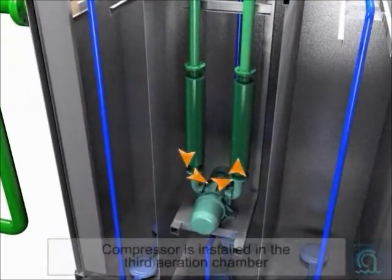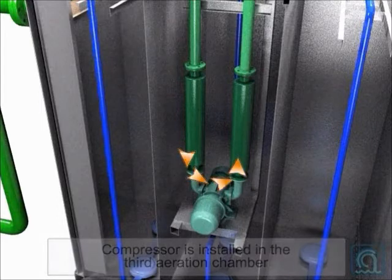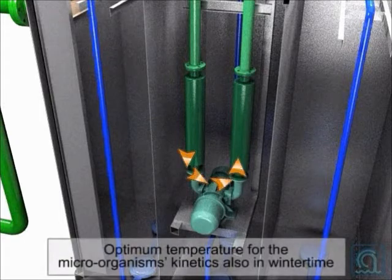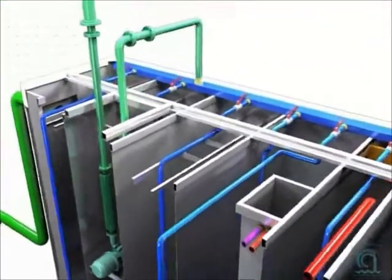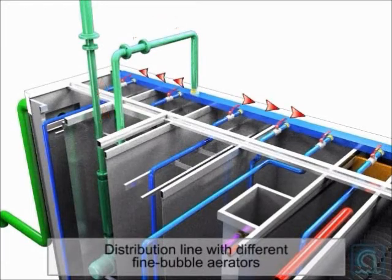The submersible compressor is installed in the third aeration chamber to reduce noise, keep the treatment plant compact, and keep the compressor running at an acceptable operating temperature. The heat generated by the compressor helps maintain the optimal environment for the microorganisms to flourish, especially in the wintertime. The compressor supplies air through the air distribution line to the diffusers.